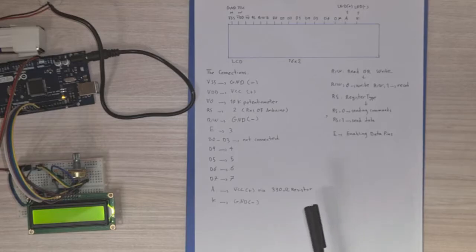Also, if we use a 4-pin data bus, it's better because the libraries we have, like LiquidCrystal, are designed for it. It can be used for 8 data pins too, but it's so much easier because it also takes fewer pins, which is important in boards like Arduino Uno.